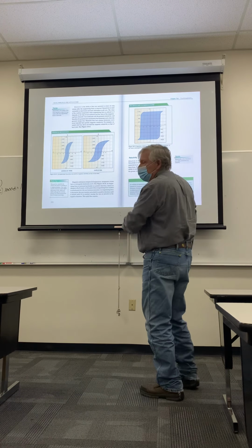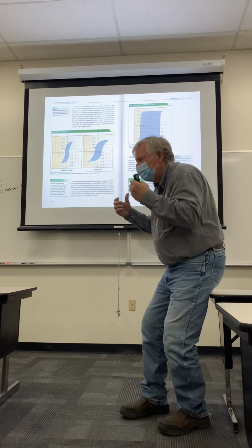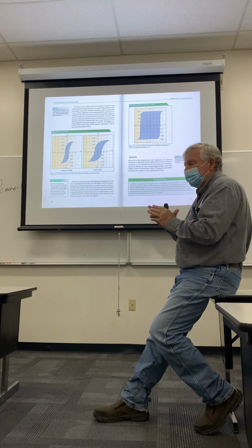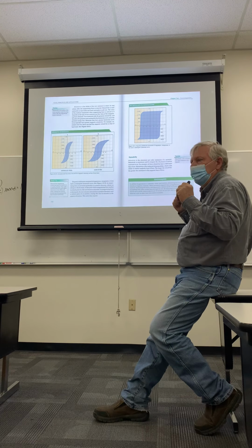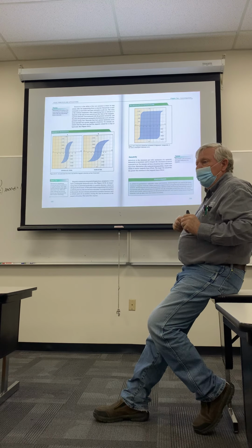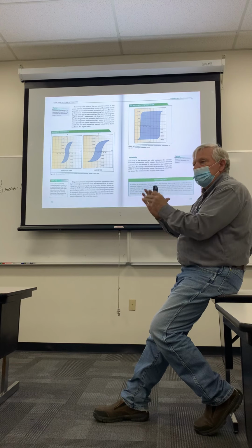Okay. So notice that the graph for the hysteresis of annealed steel is slightly different than the hysteresis chart for hardened steel. So this is something that you have to keep in your head. If you're trying to make something that you want a small hysteresis curve, something that can really be magnetized quick and then give off its magnetism, you would probably want to look at annealed steel rather than hardened steel because the hysteresis chart is smaller.